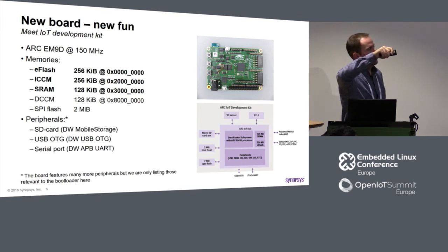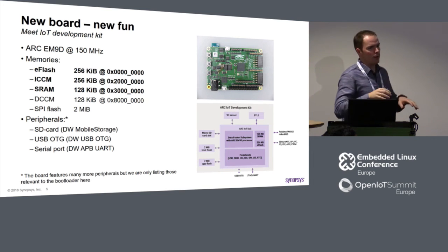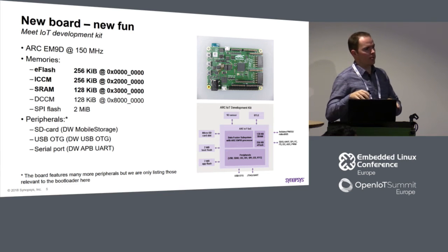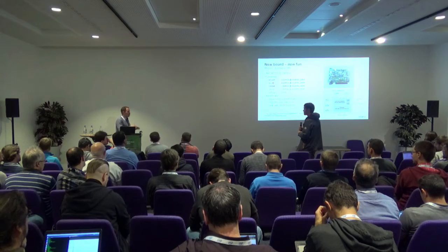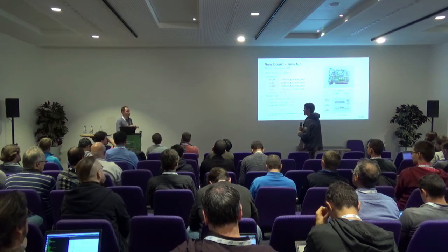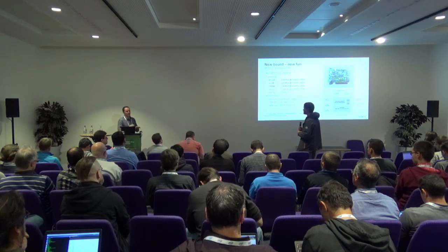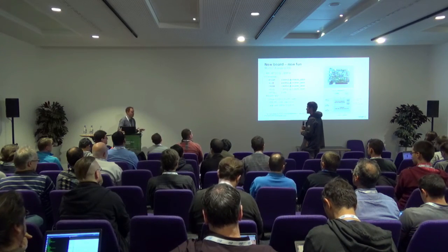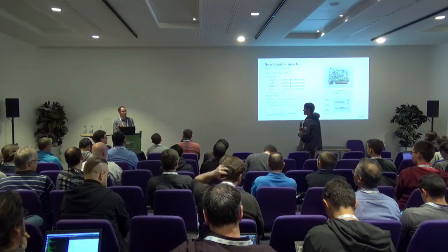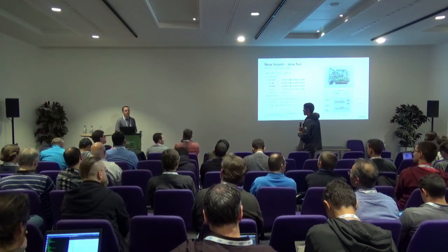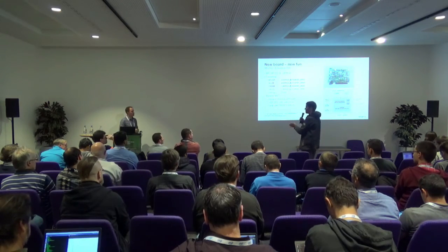In U-Boot parlance, you say fatload mmc0 mycool_app.bin and provide an address. And then you say go to the same address. And what happens, U-Boot just jumps to that location and starts to execute your application. From this point, there is no U-Boot any further. It might still exist somewhere, but you pass control to a different application, and that's the reason for a bootloader to exist. So this option doesn't prevent running bare metal, raw binaries.